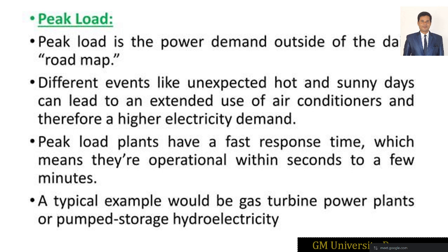As compared with the base and intermediate loads, the peak demand will be huge, where the demands occur all of a sudden. You have to satisfy the peak demand also, and that is possible through your energy storage management. Peak load plants have a fast response time, meaning they are operational within seconds or a few minutes. Typical examples are gas turbines and pumped storage hydroelectricity, which store energy and satisfy the load demand during the peak times.